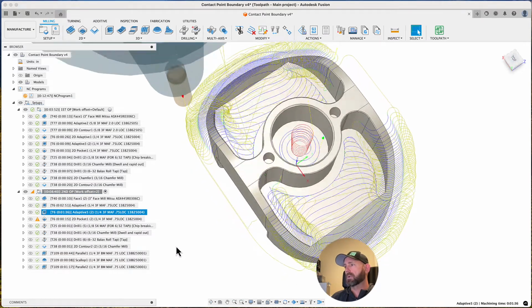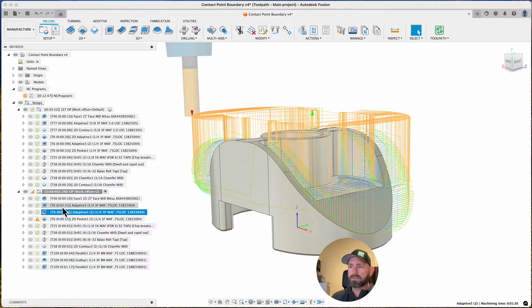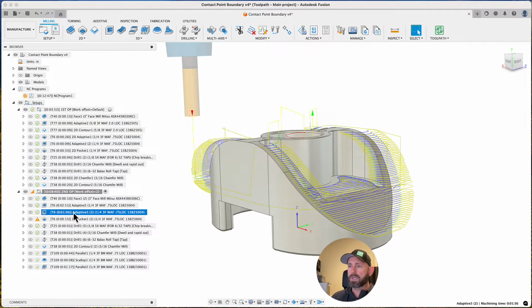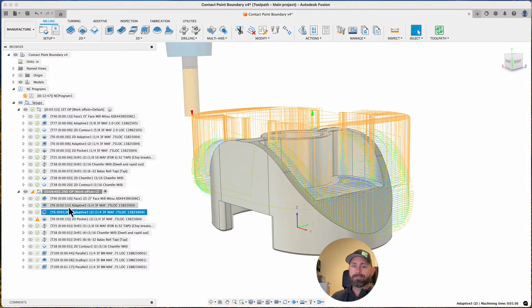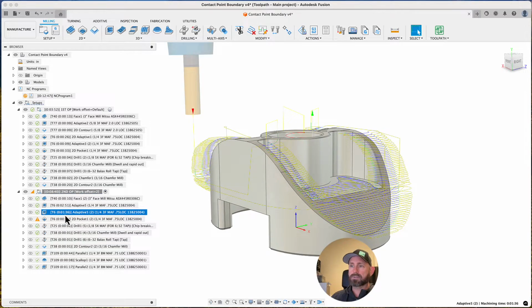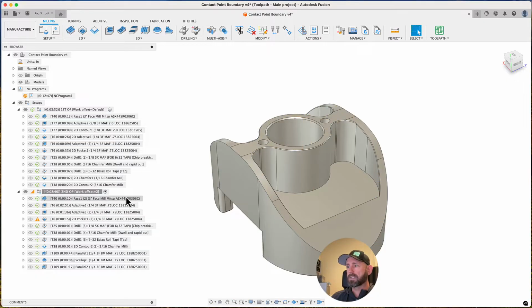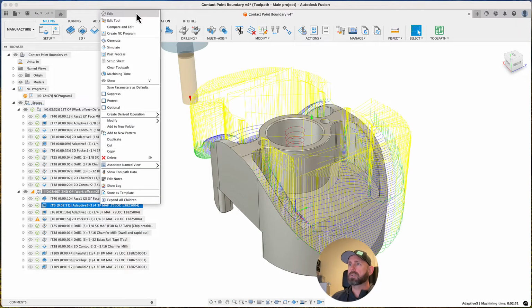This is what I would probably run out on the machine. It's 1 minute 36 seconds versus 2 minutes 51 seconds. So it's way more efficient. Doing the math, I think we're 40-something% less cycle time to do this one than it is to do this one. So let's chase those ghost cuttings first and try to understand it.